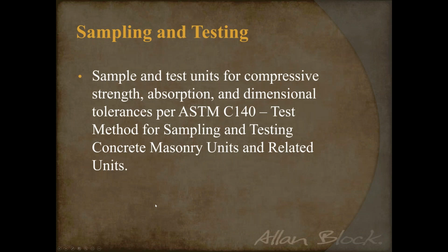So, testing and sampling of the product. Sample and test units for compressive strength, absorption, and dimensional tolerances, and they're all per the C140. This is the test method for sampling and testing of concrete masonry units and related units.